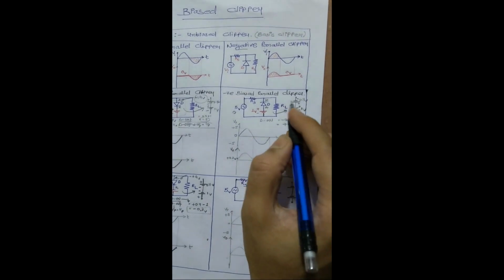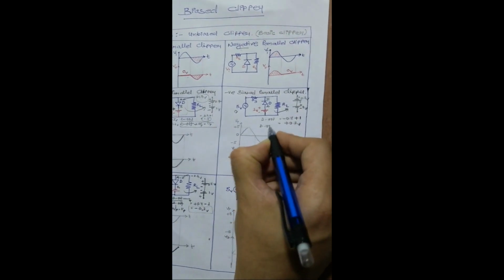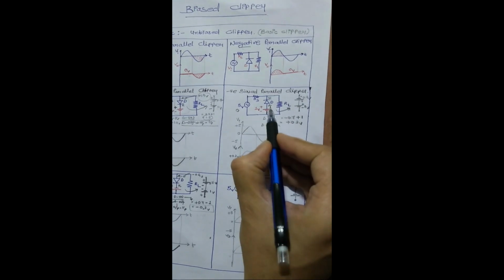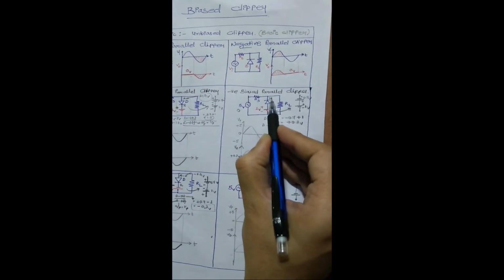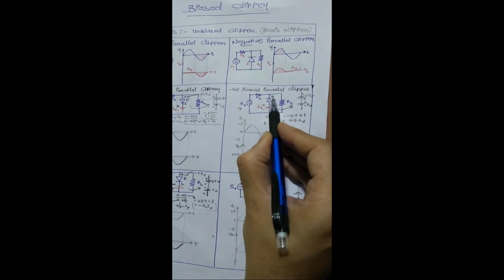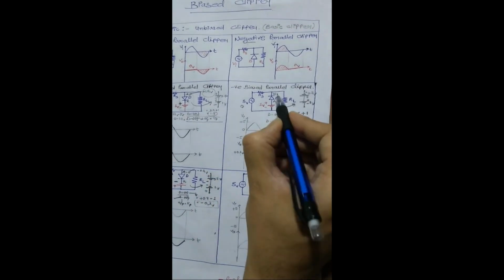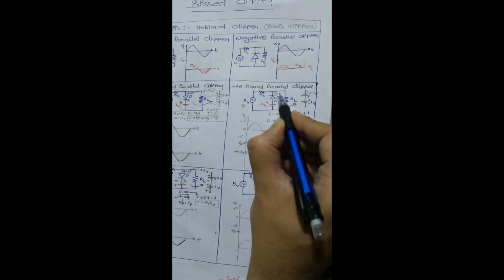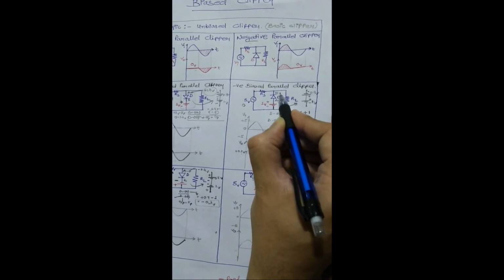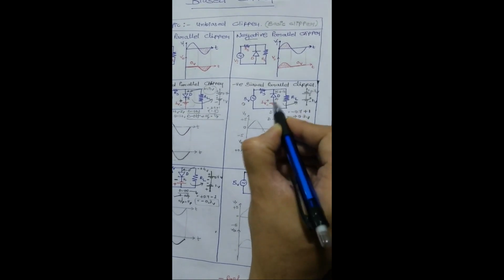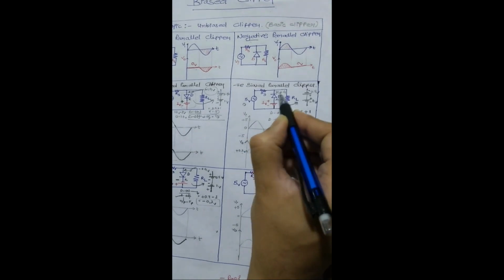So think about D off. The second question is D off. So initially anode is +1 and cathode is initially 0. So as the input voltage rises from 0 to +5, it goes 0.1, 0.2, 0.3. When cathode is equal to 0.4, the difference between anode and cathode is 0.6, hence D is off. So after 0.3 in the positive cycle, D is off.